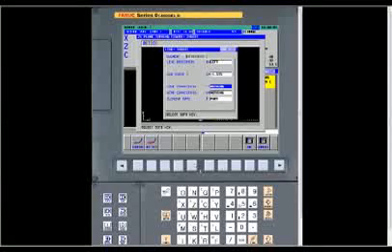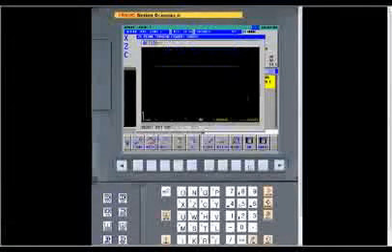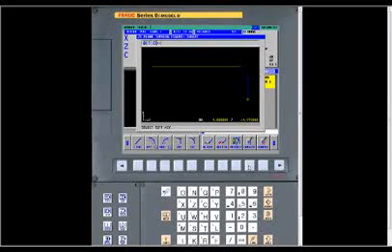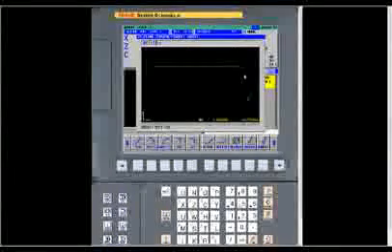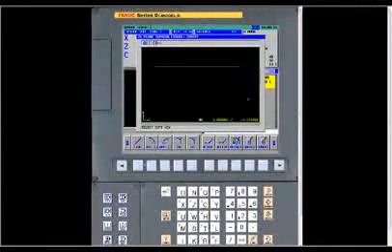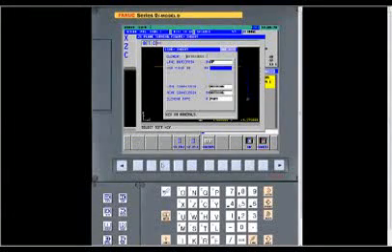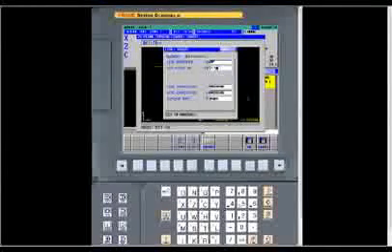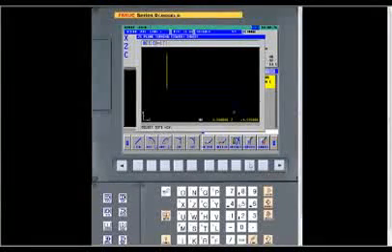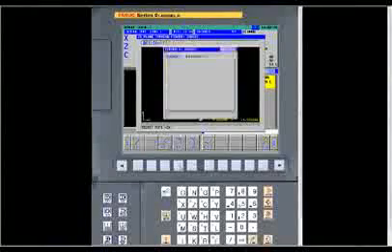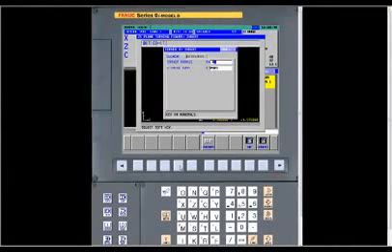Okay, again, we don't have to do anything for those. And say OK. It draws the line with the chamfer here. And we want to do a line up to 2.5. That's where we ended up on the other side. Say OK. So it draws that. We want to put another corner radius there, 60 thousandths.